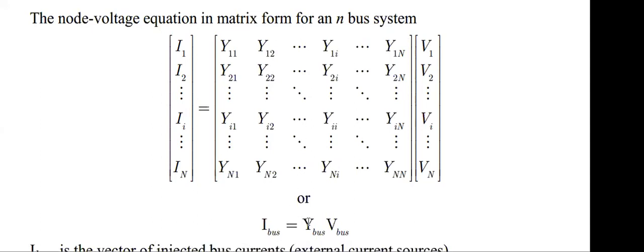No, bus matrix is actually for this Y bus. Our target is to generate this matrix. This Y bus is our objective. Okay, and to generate that Y bus, this is not actually the regular admittance, right? Just now you have seen this capital Y11 is the driving point admittance or the summation of all the admittance in that Y11. It is not individual admittance, right? It is actually the multiple admittance attached to that.